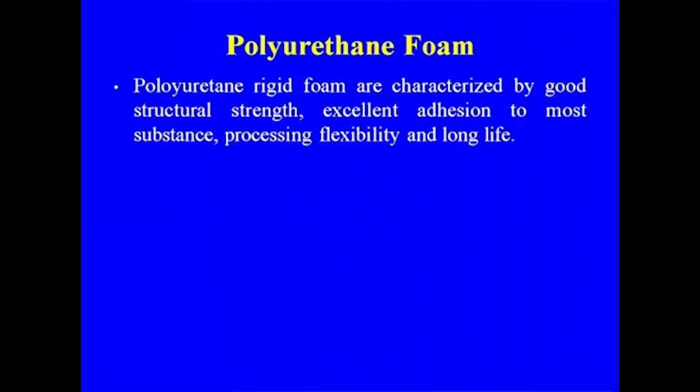Another type that has now become important in usage is the polyurethane foam. Polyurethane rigid foams are characterized by good structural strength, excellent adhesion to most substances, processing flexibility and longer life. So, these are some of the advantages in case of polyurethane foam.